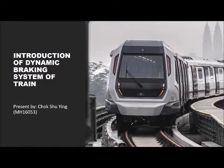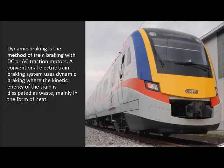I will start with the introduction of the dynamic braking system of a train. Dynamic braking is the method of train braking with DC or AC traction motors. A conventional electric train braking system uses dynamic braking where the kinetic energy of the train is dissipated as waste, mainly in the form of heat.